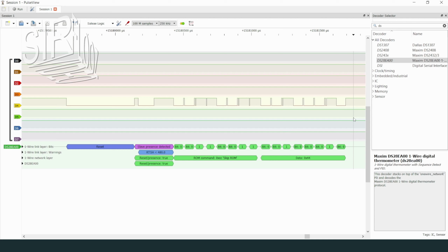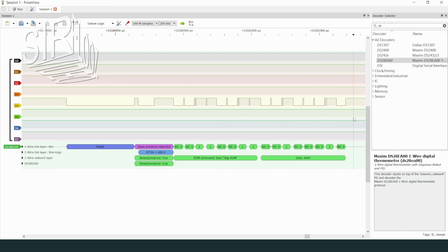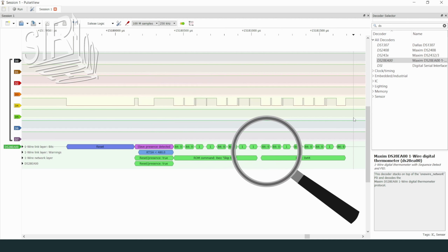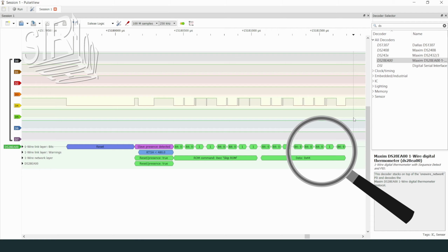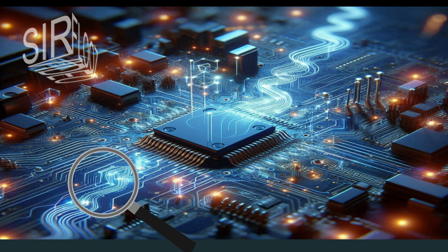What a useful tool! If you write a program and the digital communication is not working, you can use it to determine why it is not working. If you want to analyze a device, you can use the logic analyzer to listen to the data connection, e.g. between ICs, and decode it in order to understand the function.